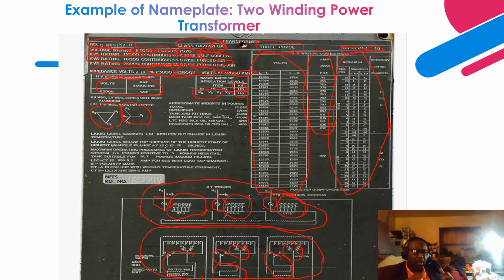Like I indicated, when a transformer is filled with oil, they fill the transformer under vacuum at 25 degrees Celsius. This is a standard utilized worldwide, and the goal is to have a standard liquid level rating for the oil liquid level indicator. What they are indicating here is that for this amount of temperature change, when the transformer picks up load and is in operation, it's going to expand and the temperature is going to change.